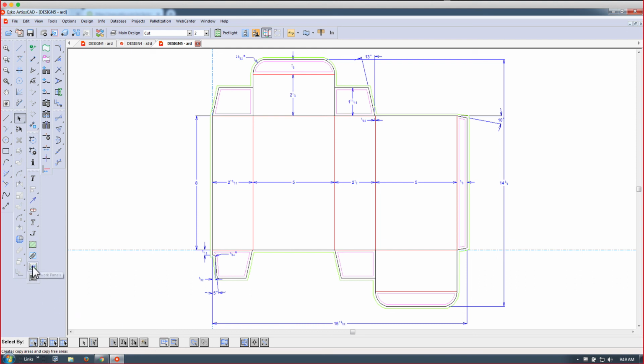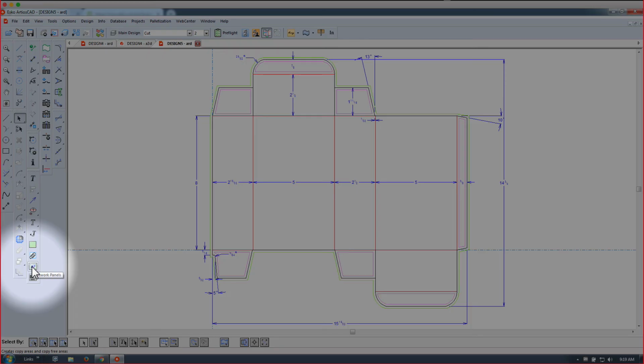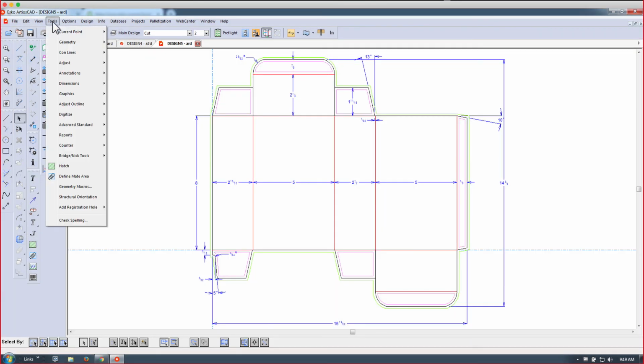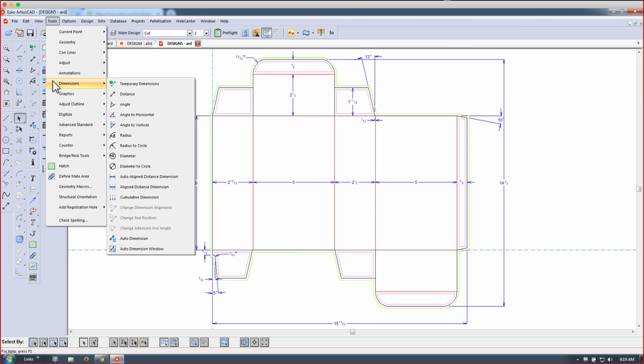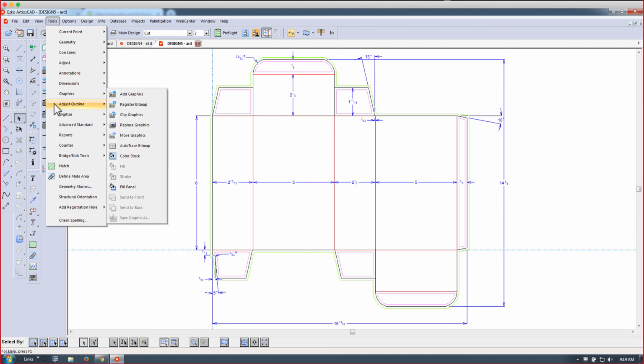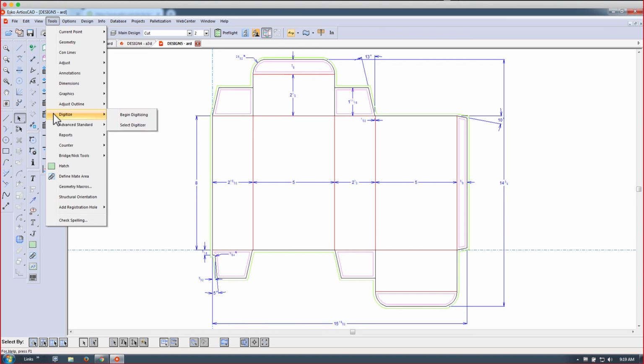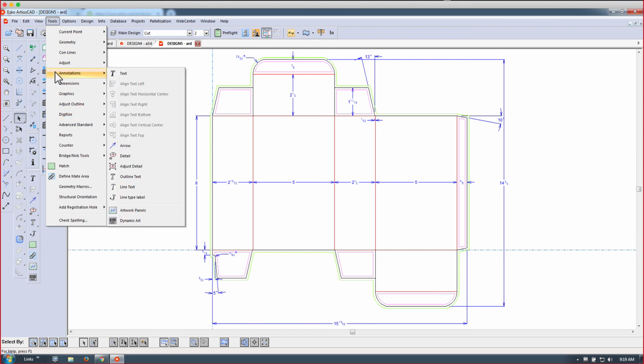Last but not least, we have what we call an artwork panel layer, which you can find here, and that's part of this toolbar. Again, if you can't see it here initially, you can always go inside your design right here, and you can access those tools again here as well. So that's in the annotation layer, artwork panels.